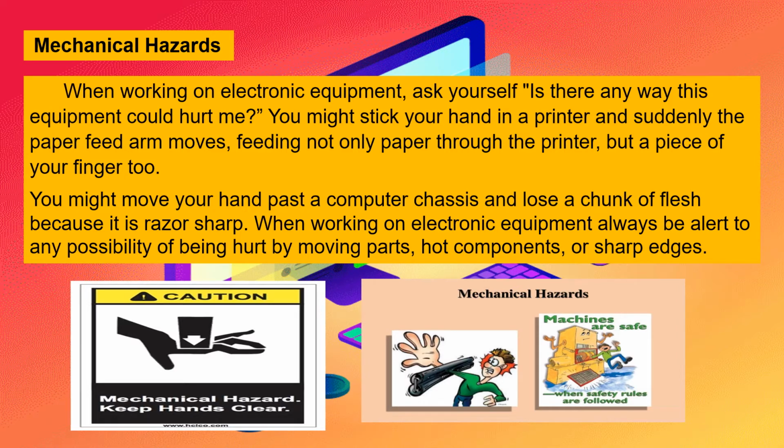Mechanical hazards. When working on electronic equipment, ask yourself, is there any way this equipment could hurt me? You might stick your hand in a printer and suddenly, the paper feed arm moves, feeding not only paper through the printer but a piece of your finger too. You might move your hand past a computer chassis and lose a chunk of flesh because it is razor sharp.